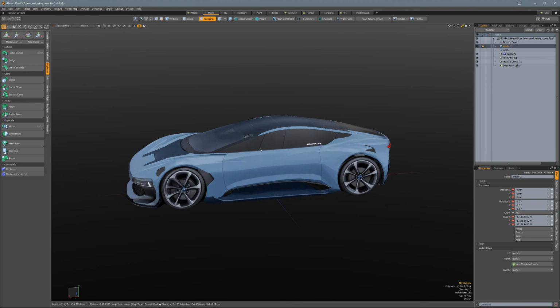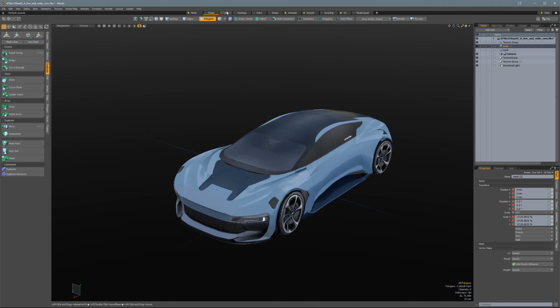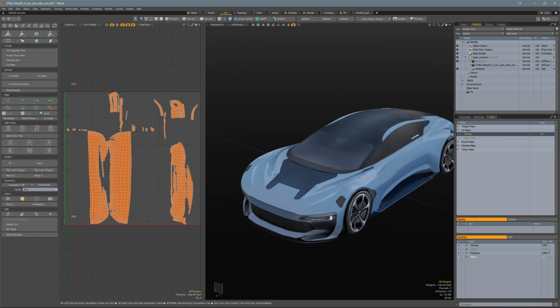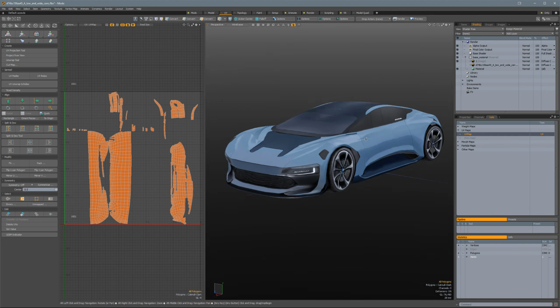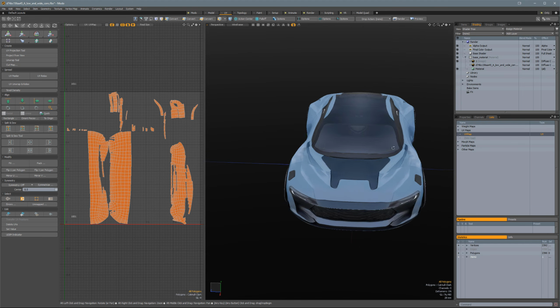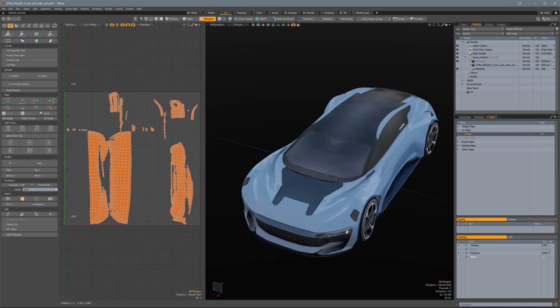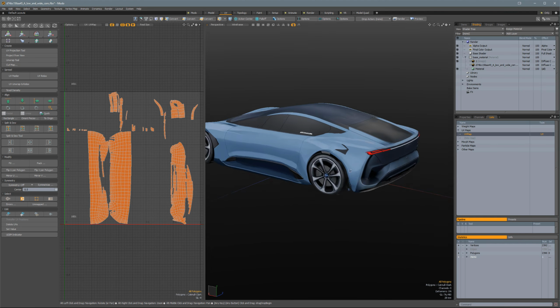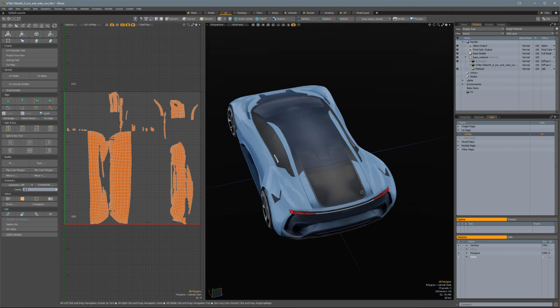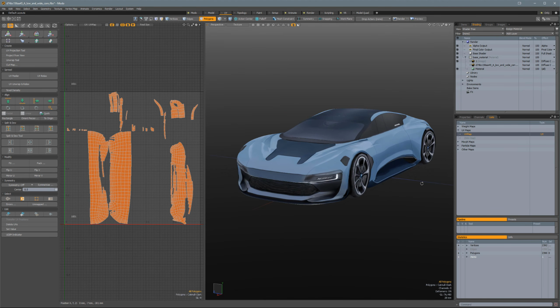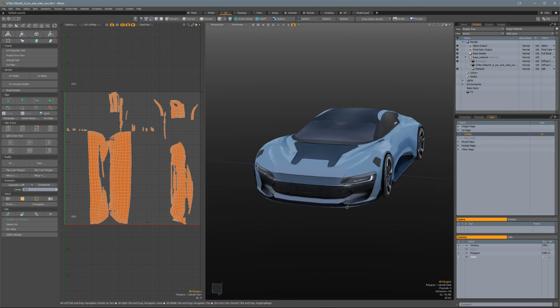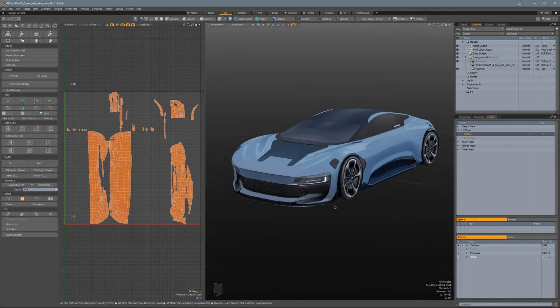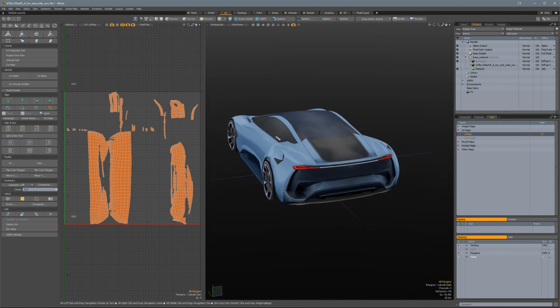Maybe you're going to come in here, make this symmetrical, clean up the UVs. Right now, the UV map for this is stacked on top of each other. It doesn't optimize the entire UV space, so you're losing some of the texture quality and the texel density. But you can always just duplicate this, lay out a new UV map, bake this up to a better map and a newer texture, re-import it into Stable Projectorz, do whatever you want. That's a whole other topic for discussion and a little more involved for people who might understand how to do that. But again, this is good for an underlay, a 3D reference, or even just a quick design evaluation.